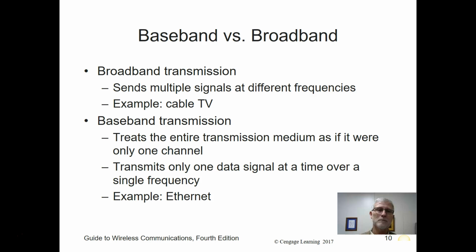So now the question becomes, how do I want to transmit this? What is broadband transmission, and what is baseband? Basically, broadband says I'm going to send multiple signals at different frequencies. Cable TV, for example. You got your cable TV. It's broadcasting 200 channels, each one at a different frequency, all in that same channel.